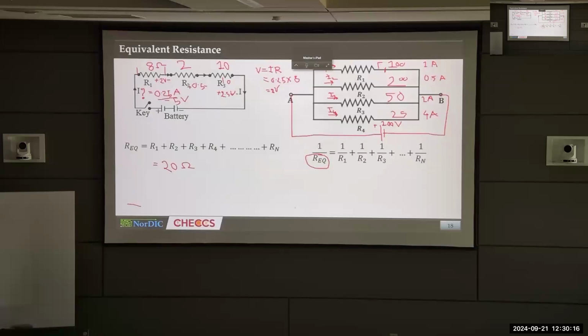It's going to take all the current you have and it will burn because it's not able to handle this infinite current because it has finite capacity. So we say, oh, I shorted the circuit. I made it a short. That means I put very low resistance on R4. So it became a short circuit.